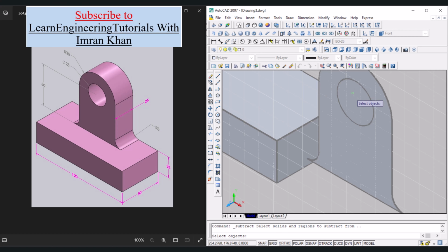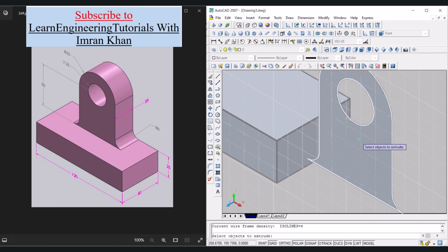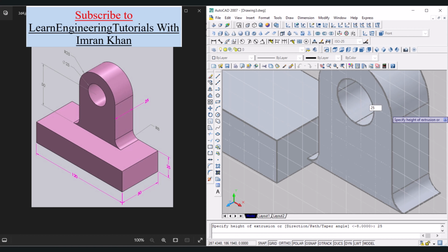Click on subtract, click on this whole body, press enter, click on this circle, press enter. Now use extrude command, so click on extrude, click on this object, press enter. In this direction the thickness or the width should be 25, enter.